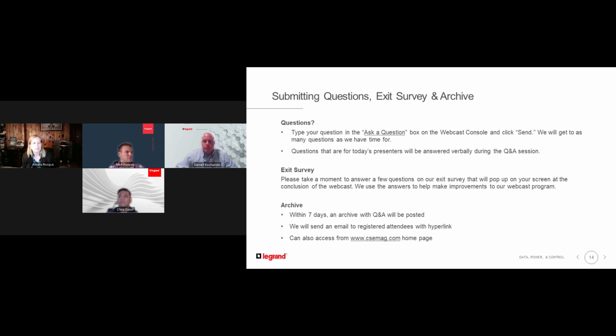All right, very good. Thank you. Chris, this next question is for you. Can you talk a little bit about the conditions where busway ampacity derating should be considered? Yeah, that's a good question. We see the majority of installs in cold aisle containment, but if you're actually installing in hot aisle, you definitely should consider looking at a derate on the busway. We have multipliers present in our spec sheets. We generally operate between 0 and 40 C as our operating range. So if you're in that hot aisle containment, you'll want to start to look at a derate above 40 C for busway.